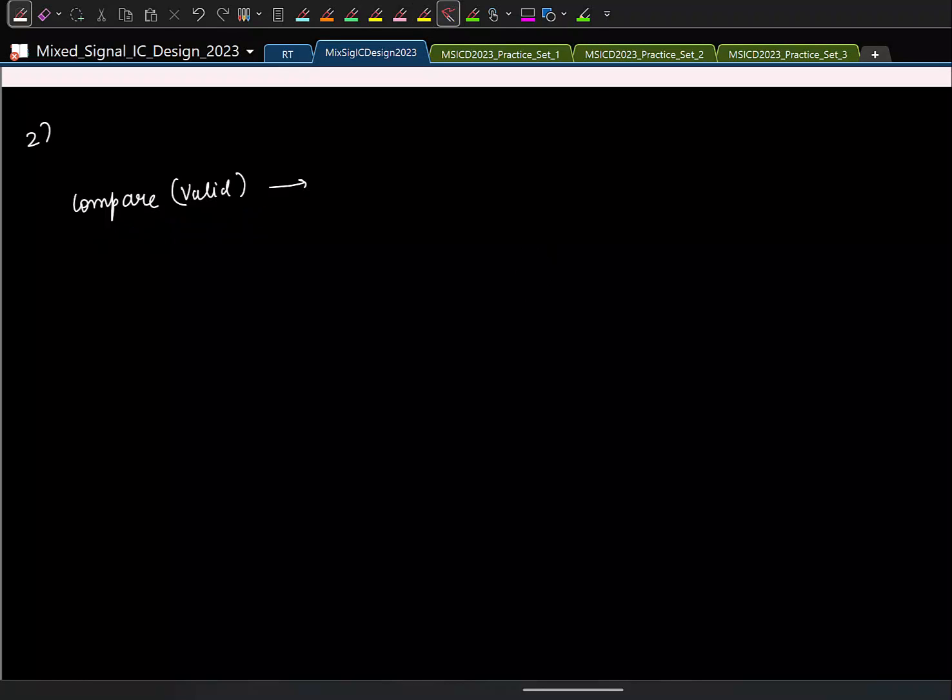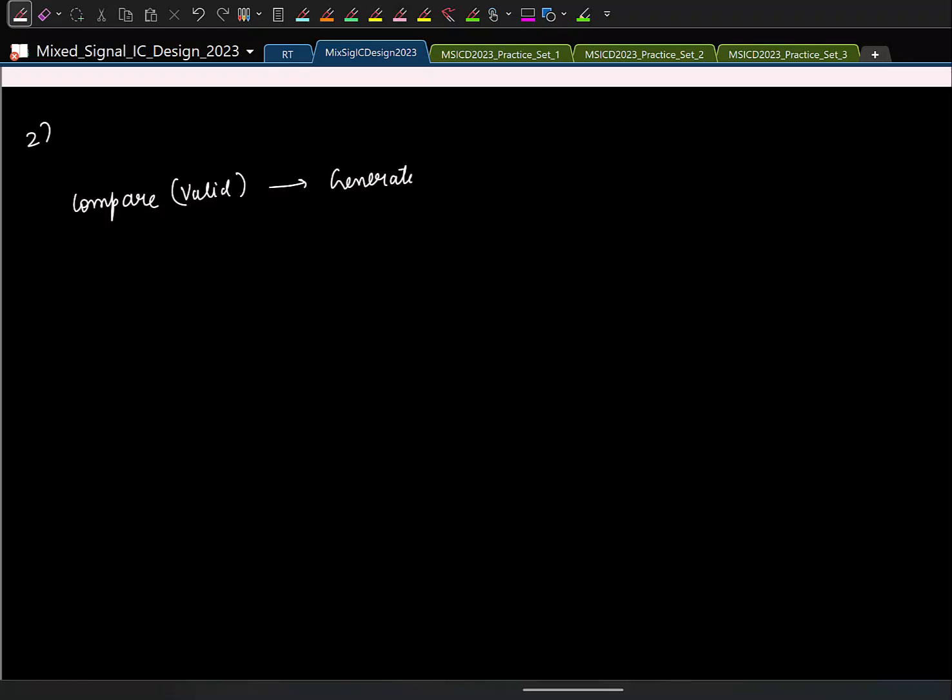After we finish making the first comparison, we have to remember that the result of the comparison has to be stored, right? And for that, we store it in a D flip-flop. The input is ready for the D flip-flop. What is the other thing that is required? Clock, right? So we generate, let us say, the clock, and then you go and store the data. And then what do you do next?